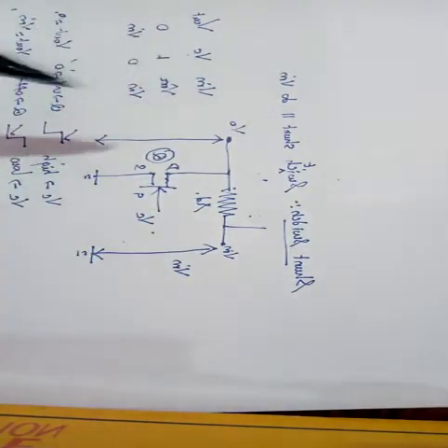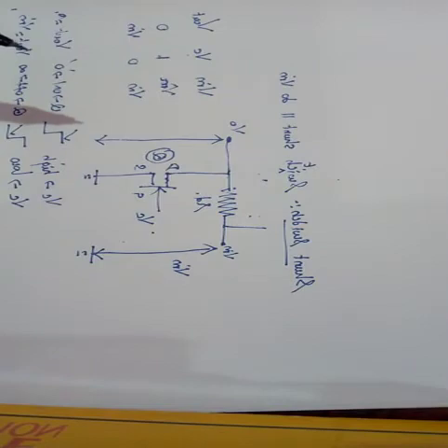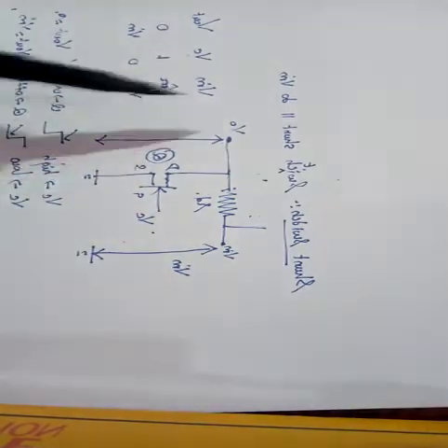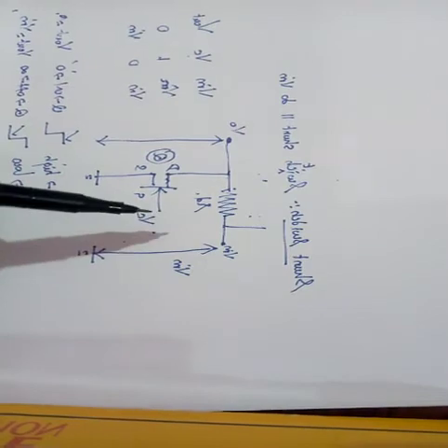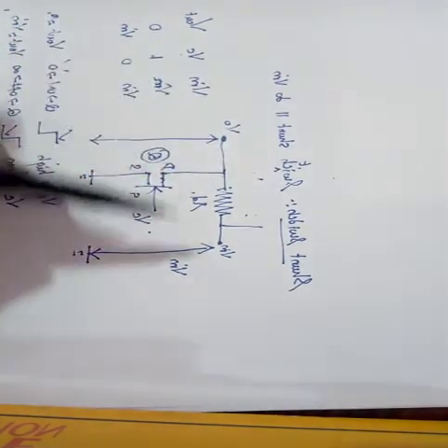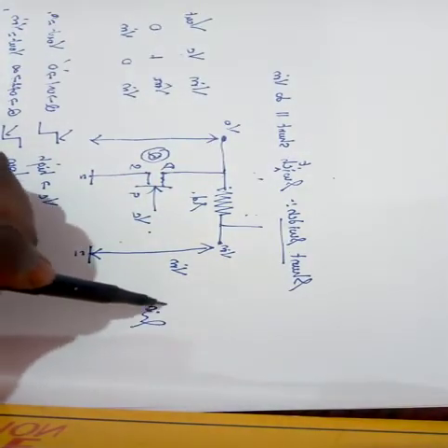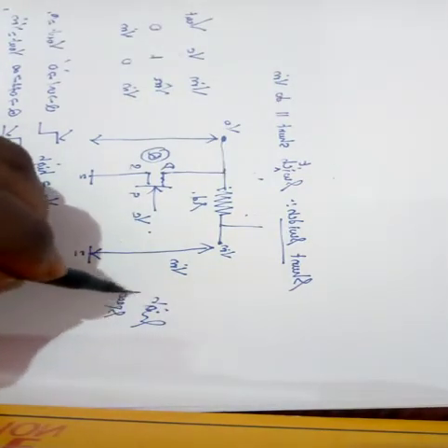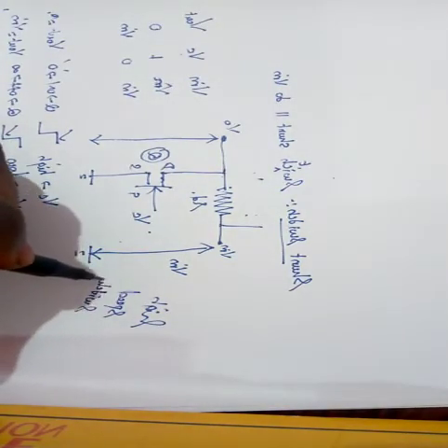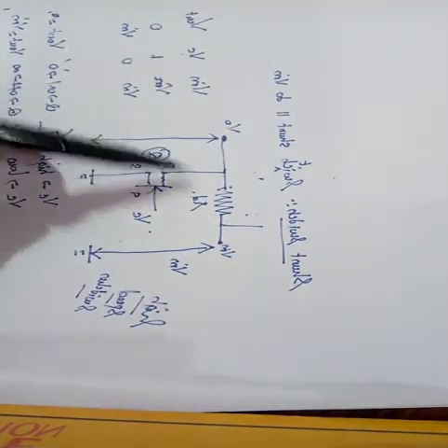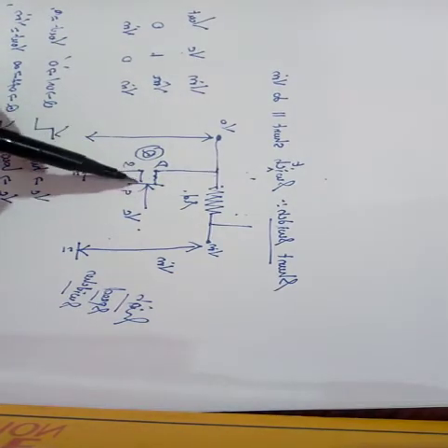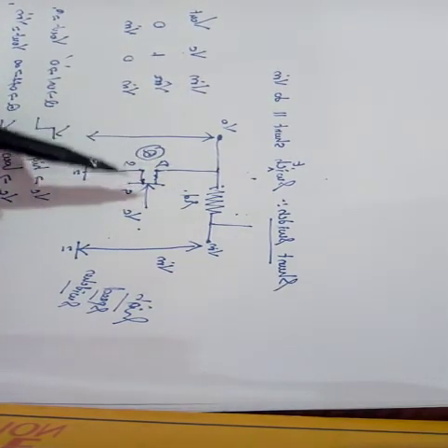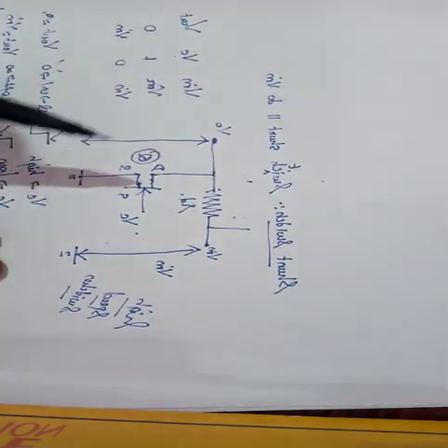So we can categorize the switch which we are going to use for sampling and hold. When we use a MOSFET or a FET switch, the switching speed is very high, so this kind of switch is called a high speed switch. This kind of operation can even be accomplished in your laboratories using a basic BC107 transistor. But for an application, kindly choose a high frequency MOSFET or a JFET.